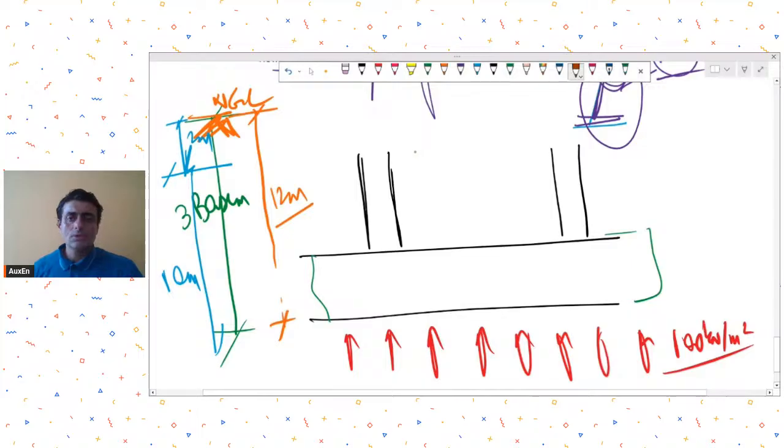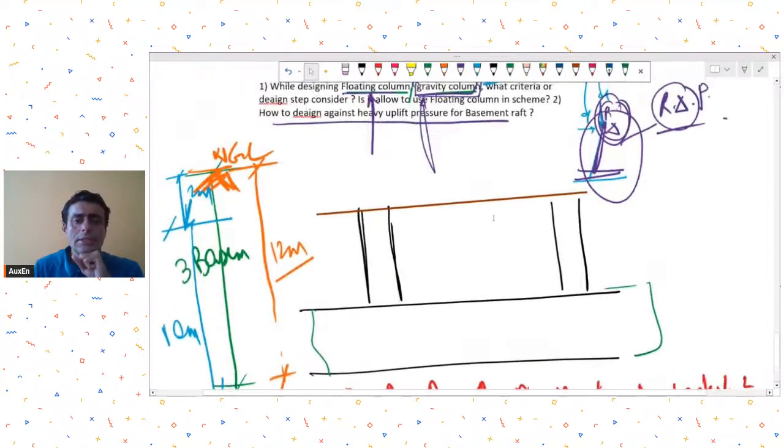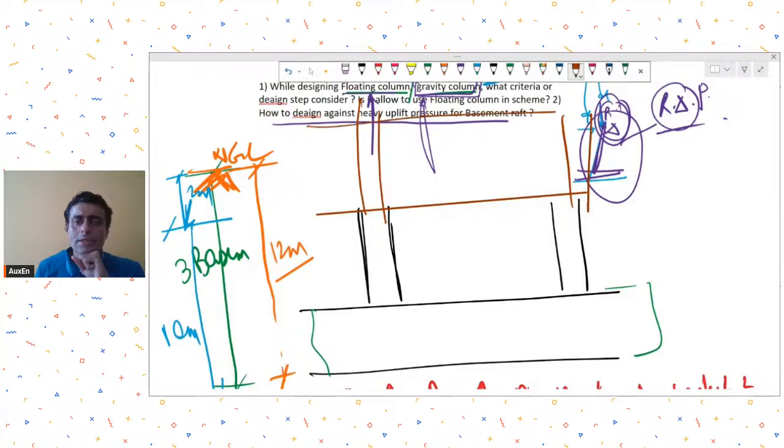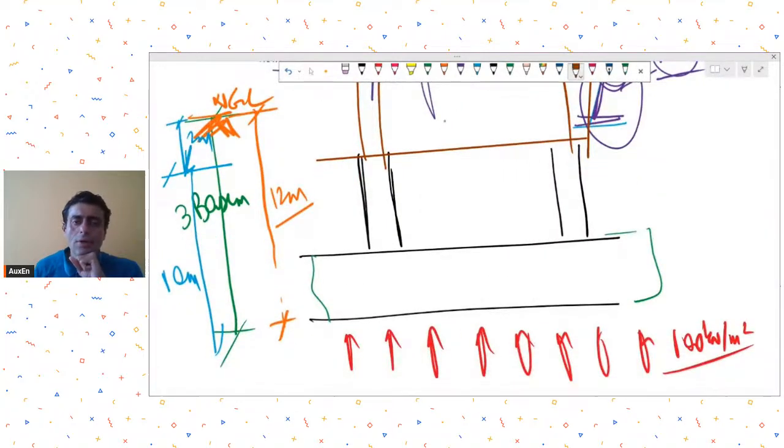Now in these cases, what you need to be careful about, that there are two things. See, if you are talking about a building which has three basements, let's say it will have 6, 7 stories above also. So when your building is constructed and all your dead loads are in place, then in the raft you will get some substantial pressures, isn't it?